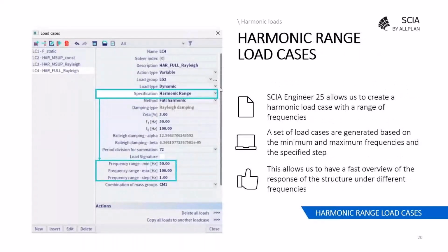Another new possibility is to create a harmonic load case with a range of frequencies. When we do that, a set of load cases is generated based on the minimum and maximum frequencies that we specify and the step that we introduced. For example, here you can see an image where the minimum frequency is 50, the maximum one is 100 Hertz, and we have a step of 1 Hertz.